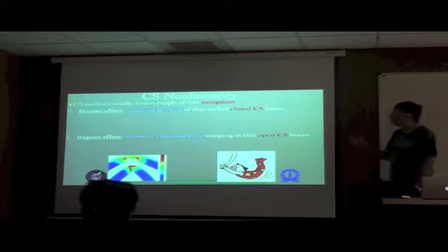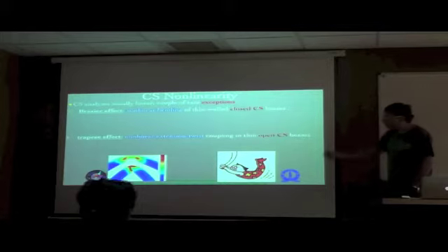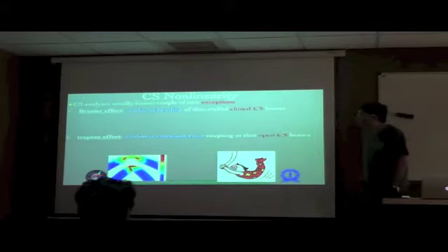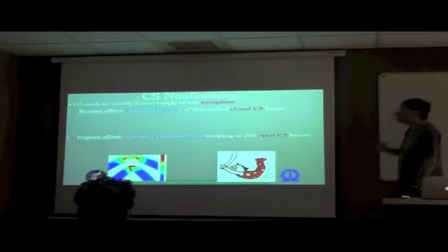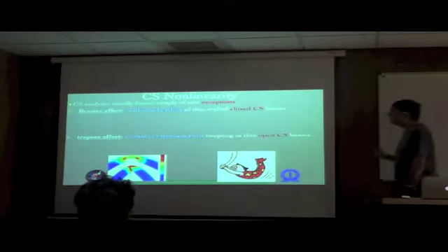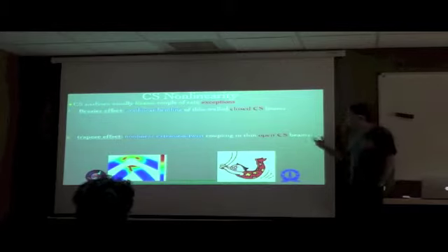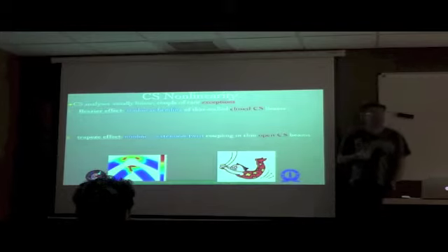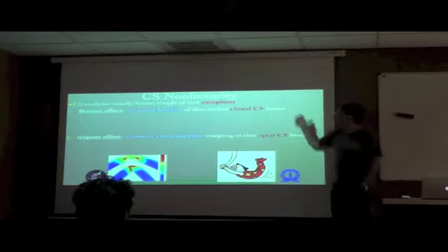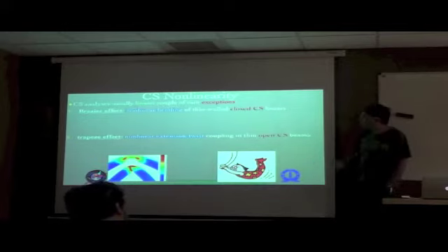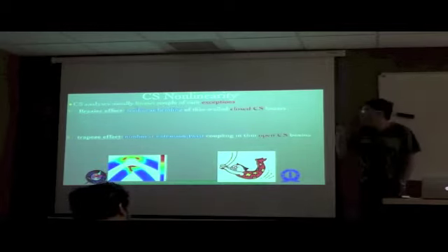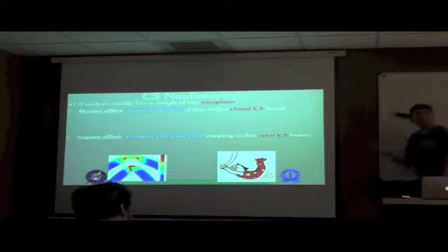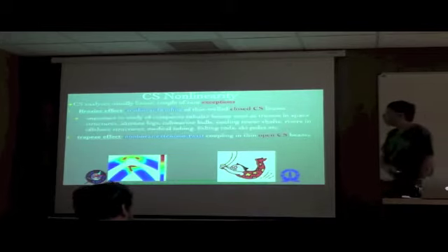But one such aspect is, for example, torsional buckling, which of course happens when this axial load is compressive instead of being tensile, as in this particular case. So this trapeze effect primarily is a nonlinear extension twist coupling, and this is something which is more commonly observed in open cross-section beams with thin walls. So whereas this is for closed cross-section beams with thin walls, here it is open cross-section beams which are thin, typically like I sections, channel section, C section, etc.